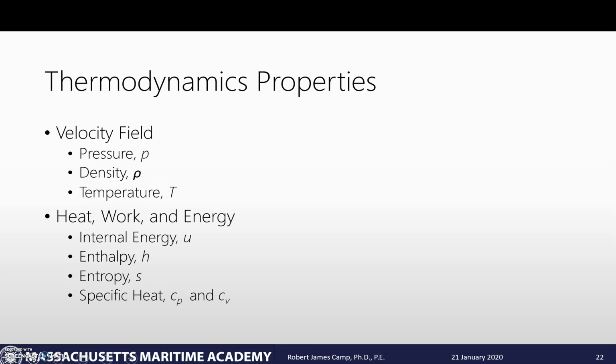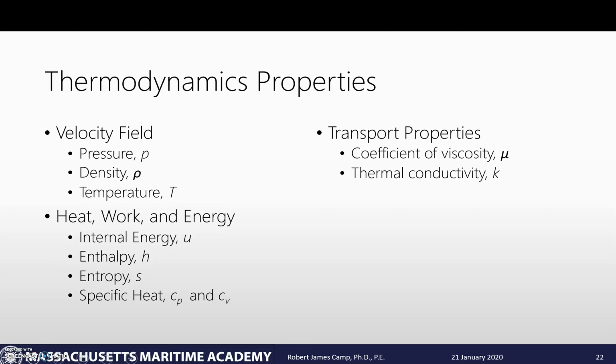So we go beyond that. We also have the heat, work, and energy properties: internal energy, enthalpy, entropy, specific heat, based on constant pressure and constant volume, all that stuff that you've got from your physics class and your thermodynamics class. And also what we call the transport properties of the fluids, and that's really the properties that deal with how fluids move. So we have our viscosity, which we'll be talking about during this week of lectures, but we also have the thermal conductivity, and that really comes about from the convection heat transfer, which is a heat transfer based on fluids moving.